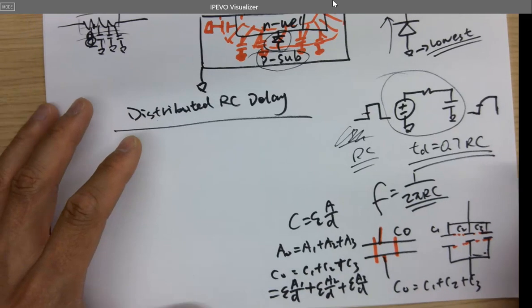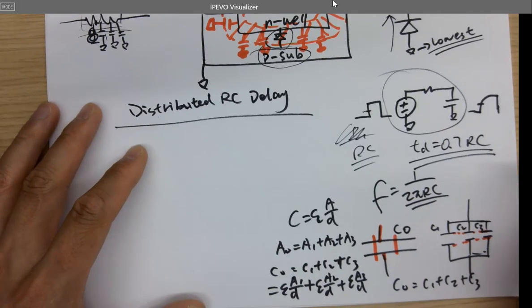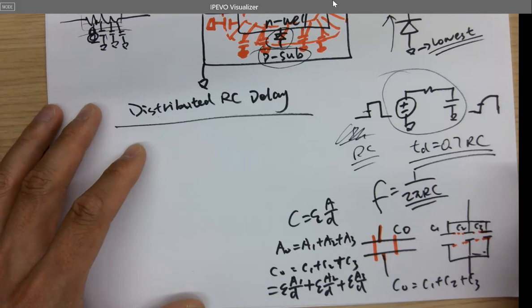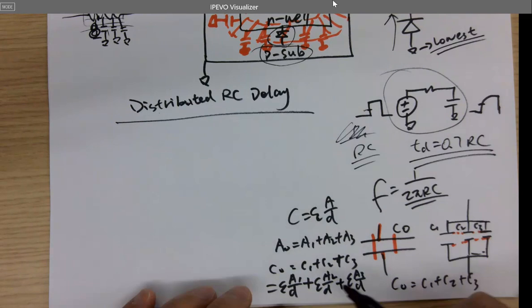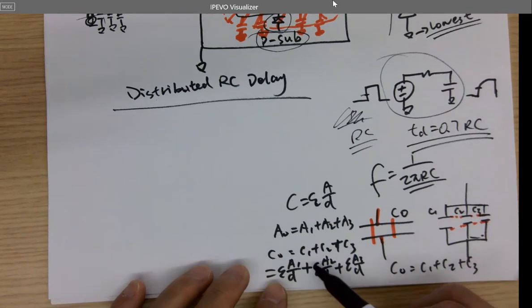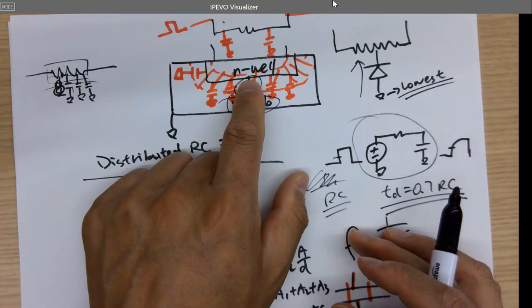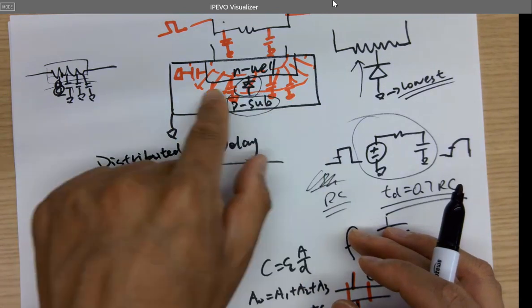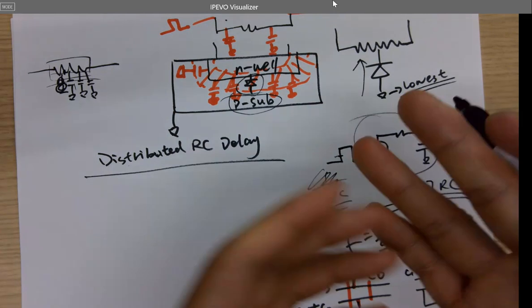More space efficient, what does that mean? Why? You are not changing it. I don't think you are changing it, because the areas, the footprint, will eventually be added together, right? So it's going to achieve the same capacitance. It's just the same area. It's not changing anything. So now we are not designing a capacitor, because these are parasitic capacitors. This is not a capacitor, definitely.